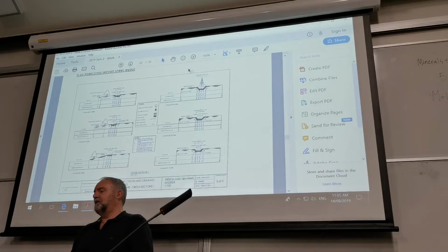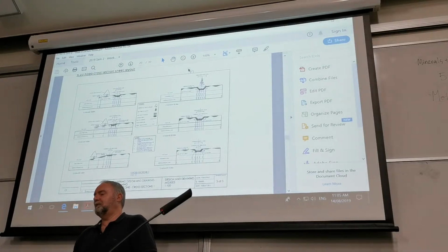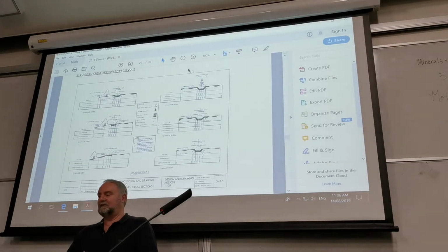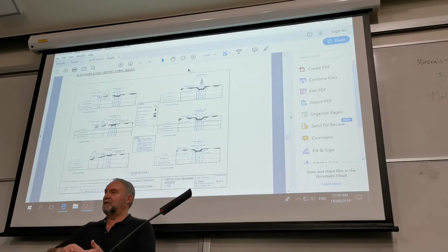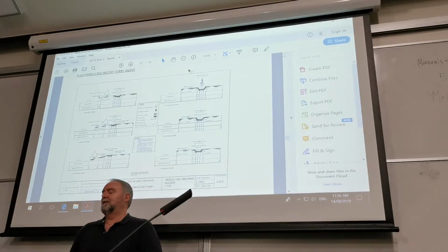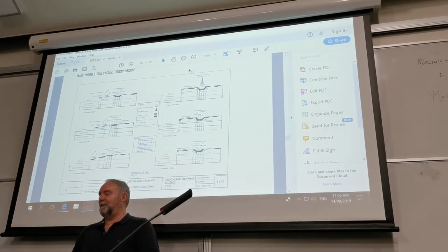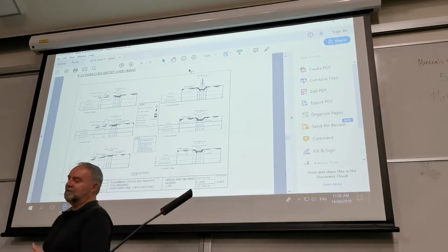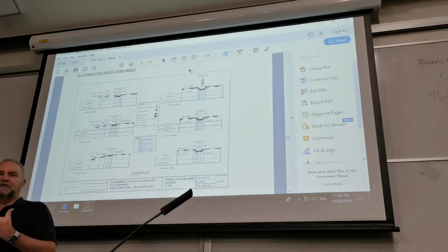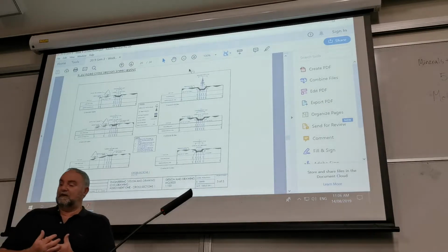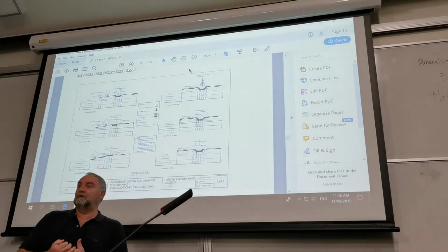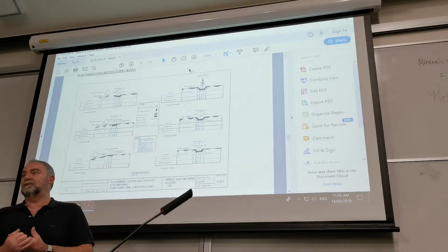So there's the first difference: the fact that they're one-to-one and they're used more predominantly on site. The long section is kind of laid out in the office, gives everyone a rough idea of the road. Remember, it's stretched. We do other things for long sections, but the other thing is with cross sections, they're normally at a different scale, a bigger scale, so we can see them better. So I've made you do that with your platforms. And when we do the roading job, they'll also be at a different scale.